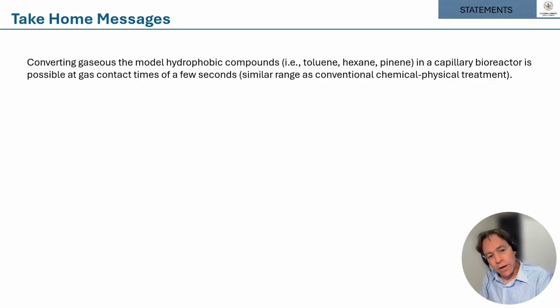Now, another area that we looked at is dilute methane. Approximately 55% of all the anthropogenic methane emissions have concentrations below 5%, and that's the lower exposure limit of methane in air mixtures, and are therefore incompatible for energy recovery or cost-effective abatement.